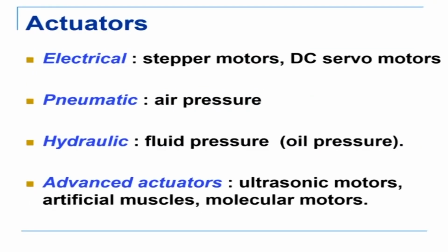In the last class, we looked at the various kinds of actuators which are there, and we can very briefly classify actuators as electrical actuators, pneumatic actuators, hydraulic and advanced actuators. And I explained that depending on the kind of torque that is required, you can use either electrical, pneumatic or hydraulic. Hydraulic is the strongest, which gives you the maximum power output, and industrial manipulators which carry very heavy loads like 50 kg, 100 kg, very often have the base link of the robot actuated by hydraulic actuators.